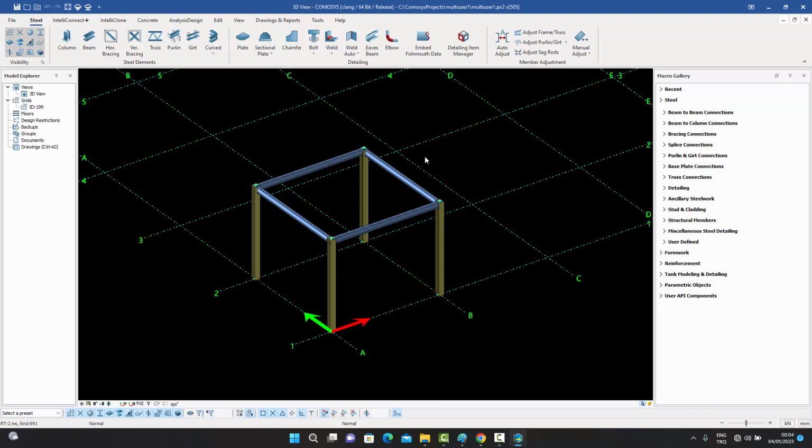This is, of course, a very simplistic example, but typically with large multi-storied buildings, you can divide the building into stories. You can assign story 1 to user 1, story 2 to user 2, story 3 to user 3, and so on and so forth. By using this, you can reduce the man hours, because what can be done in a month, you can do in 10 days with 3 users working on the same model at the same time. This is a very nice technology to have.